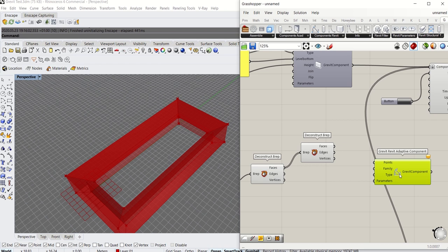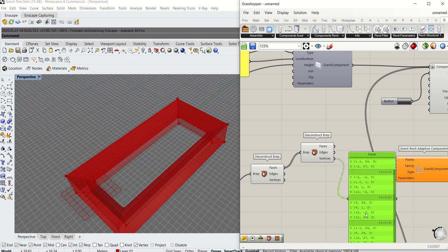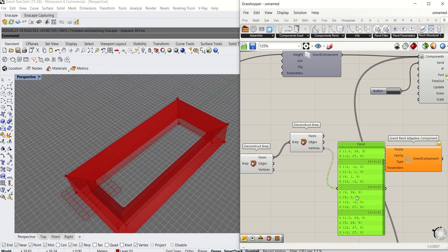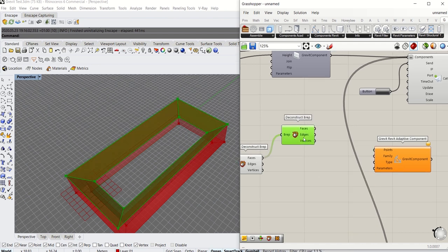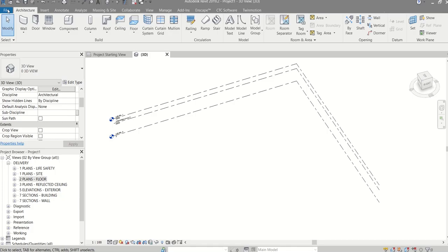Then now, if you get panel, you get 4 different untrimmed surfaces, as well as 4 different sets of point lists. So that's what we need, and that goes to points. Okay, now we'll have to go back to Revit and generate that adaptive component in Revit and create